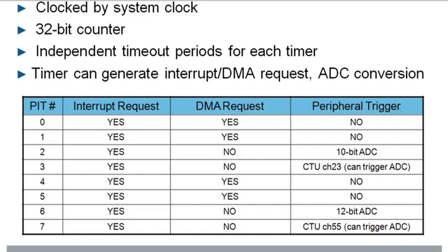And we're going to talk about DMA later, but let me just give you a little teaser on DMA, which is direct memory access. DMA is simple. Normally a peripheral flag asserts for an interrupt request. It says, hey, I want an interrupt, and the CPU, when it gets to it, it's enabled, says, okay, what do you want? And the CPU saves registers and then does something, and then restores registers and goes back to what it's doing. On a DMA request, the peripheral asserts its flag, and if you select DMA instead of interrupt, then a transfer is done from A to B of whatever you've specified or previously described.